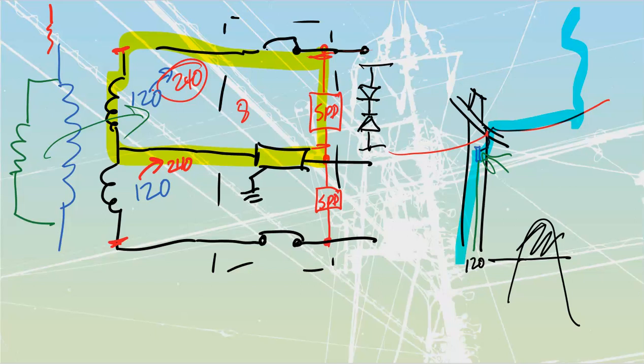The first one that they have over there is called the MCOV, the Maximum Continuous Over Voltage. And they say that this is the AC or DC voltage above which the SPD will provide clamping. This value is chosen according to the rated nominal voltage of the system. There's a typo inside of that sentence. It is above which the SPD will not provide clamping.